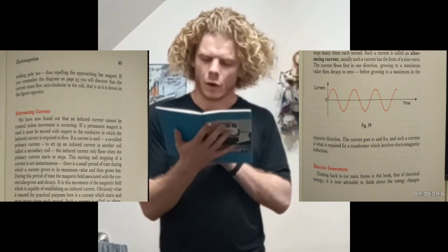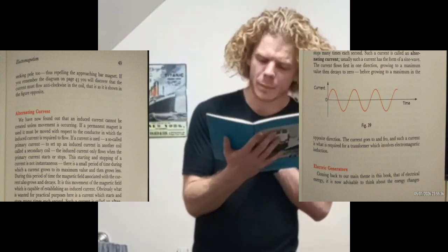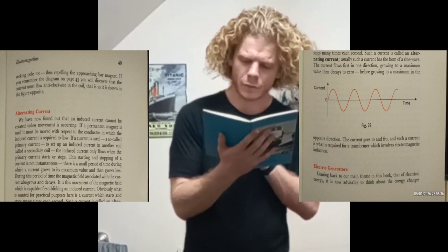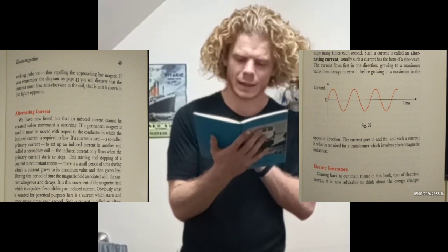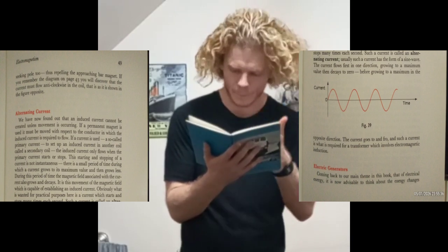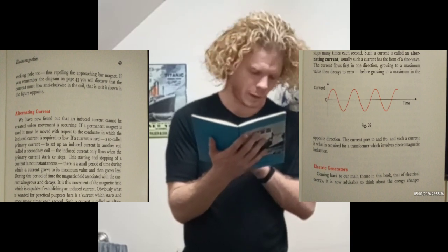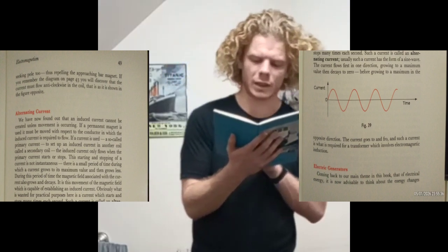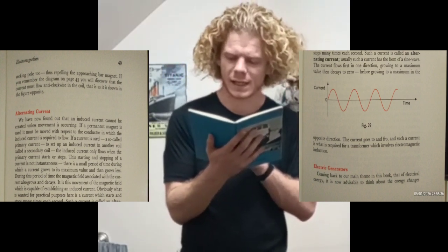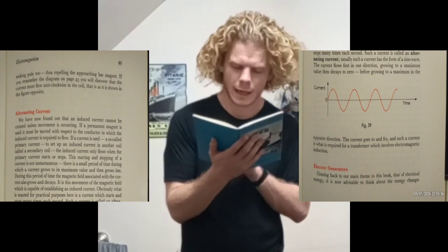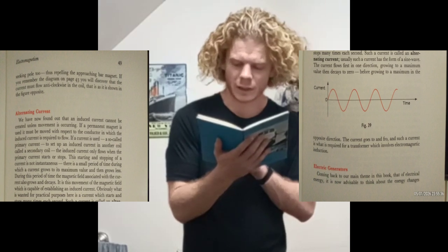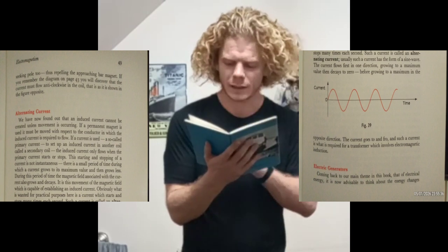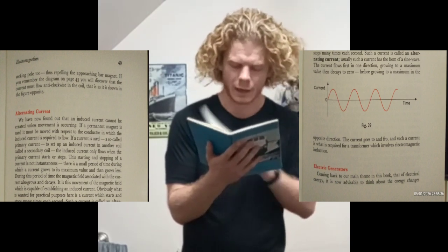You will already know that iron is more permeable to magnetic lines of force than air. It is easier for a line of force to pass through magnetic materials, to permeate them, than it is for these lines to pass through non-magnetic materials. This can be illustrated simply by using iron filings to show the field existing between two unlike poles, and the alteration in the field when a piece of soft iron is placed between the poles. The lines of force crowd into the piece of iron.